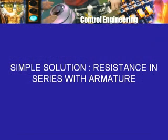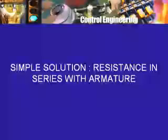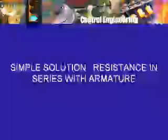Now what if such an applied voltage is not available, because you are getting commercial supply which comes at only 230 volts value? This problem arose a long time ago, and there is a simple-minded solution, namely if you need a smaller voltage, then in series with the armature connect a resistance, so that the voltage across this resistance will reduce the applied voltage. But you can see that the thing is not desirable.